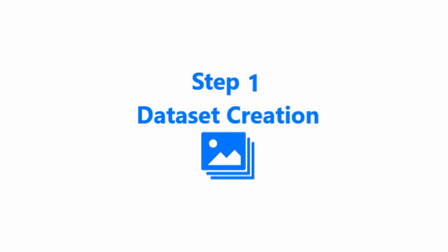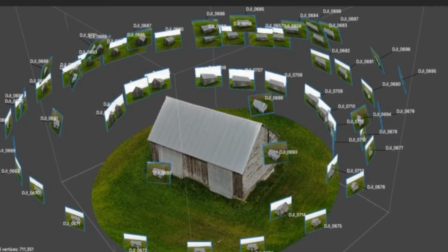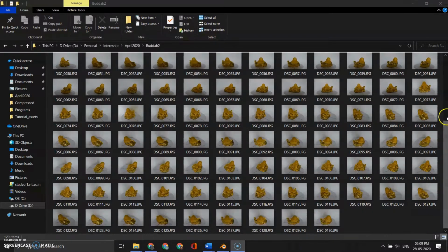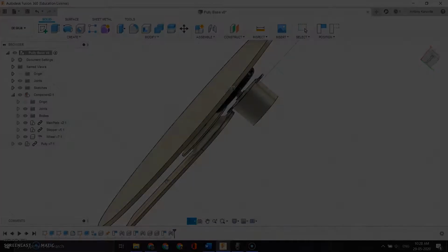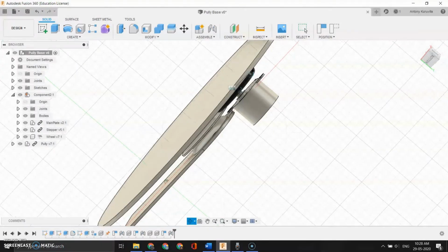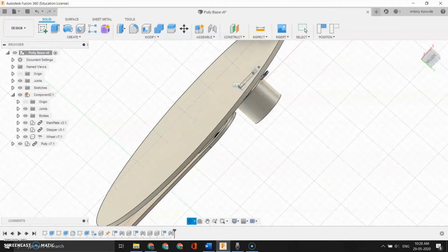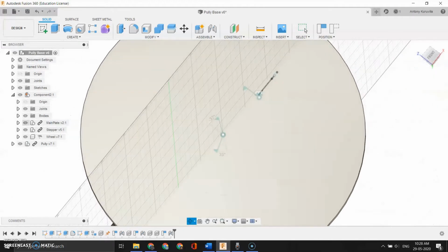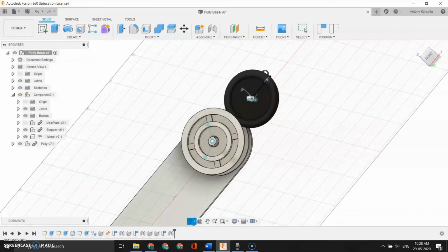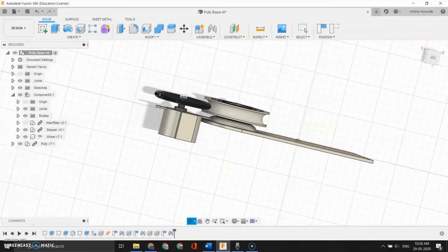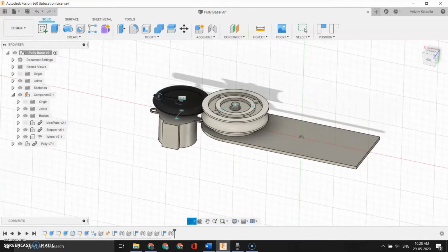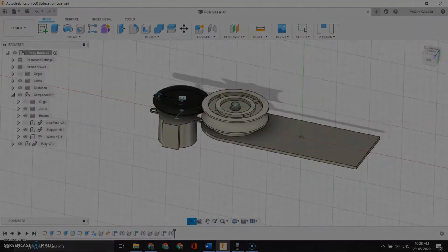The first step to obtaining a good model is creating the dataset, which is also the hardest step. The dataset must contain images of the object kept at various angles, and depending upon the complexity of the object, may require 50 to a few hundred images. In order to obtain these images, I designed a system that uses a stationary camera and a rotating platform. The platform is mounted on top of the white wheel with the motor connected to the wheel in a gear-like arrangement. I connected the motor to the rotating platform indirectly in order to prevent excess strain on the motor in case something too heavy is placed on the platform.